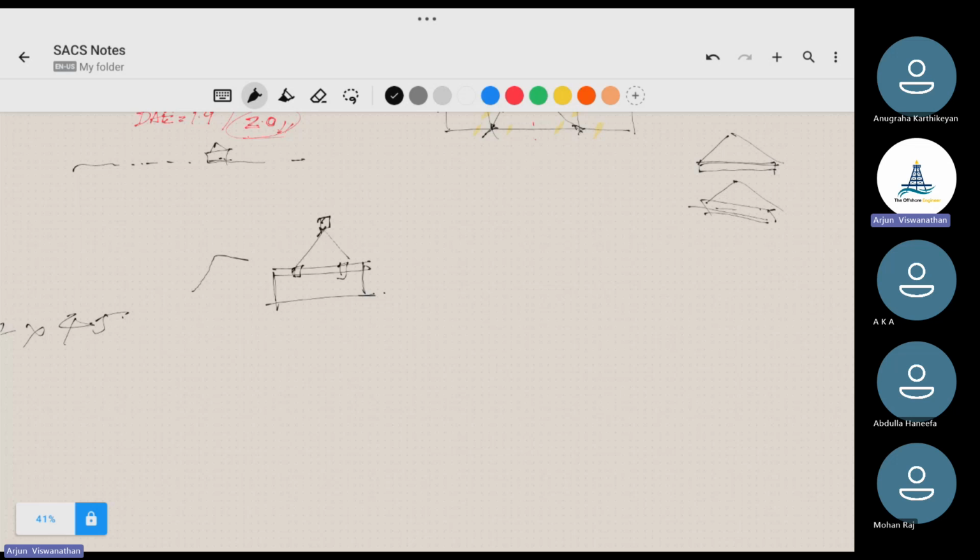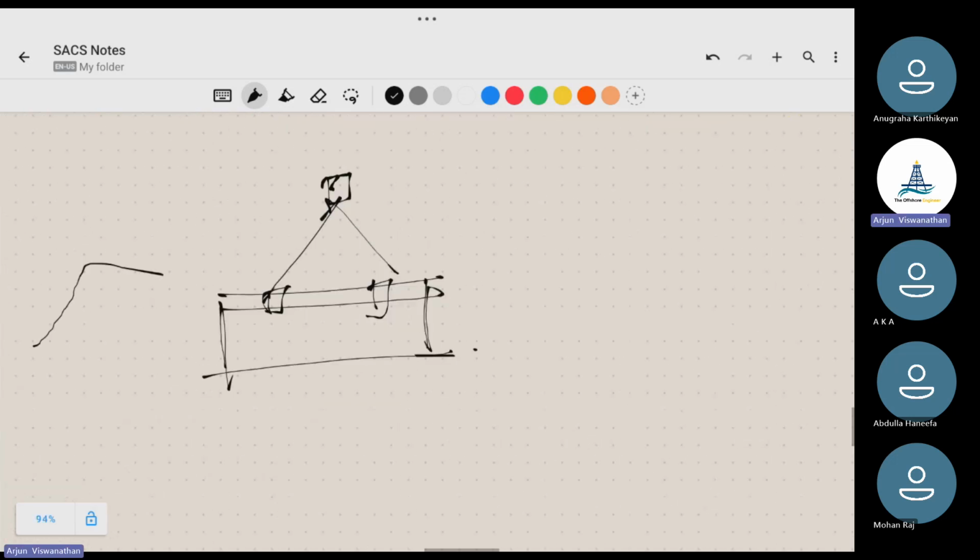When I draw this sling, one normal consideration is the angle the sling makes with the horizontal, in the plane of that sling. When I draw from the side, I can show it like that. That angle should be a minimum of 60 degrees.